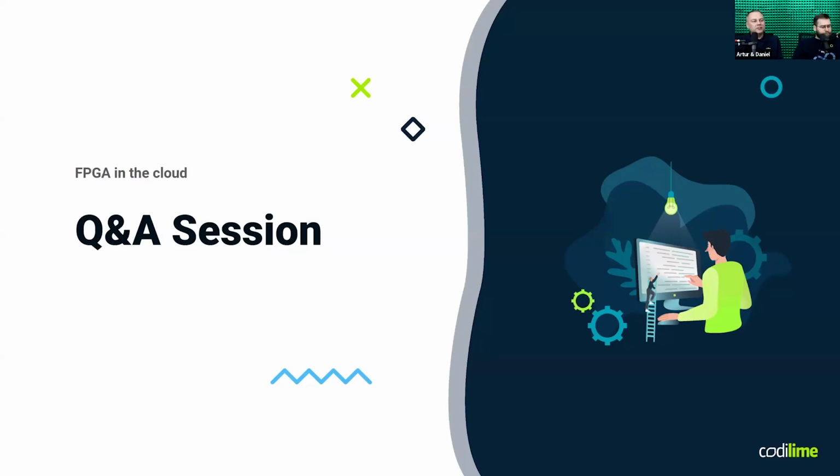please keep in mind that eBPF in the kernel is not a virtual machine itself. It is some kind of interpreter. It takes the instruction and jumps through the instructions, doing what each instruction shall do. In this case, the FPGA will actually do it faster, because it is clocked by the clock and the RTL logic is doing the operations.